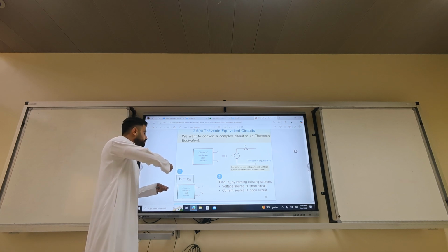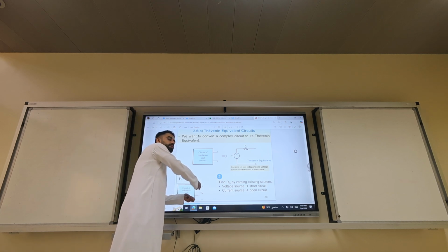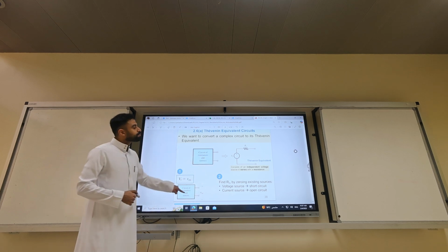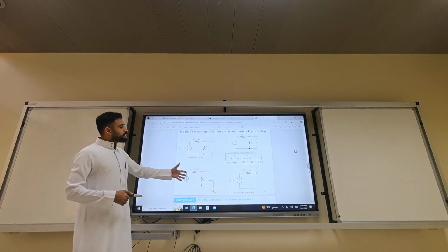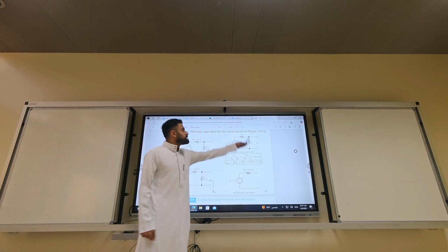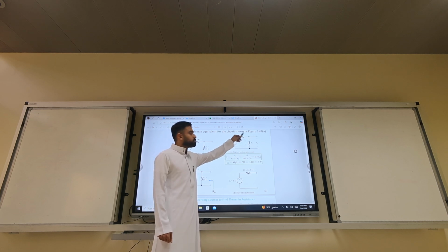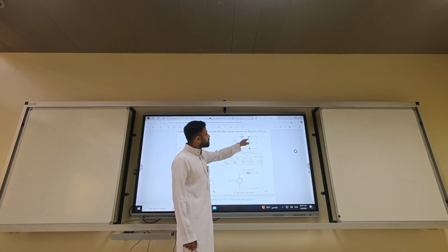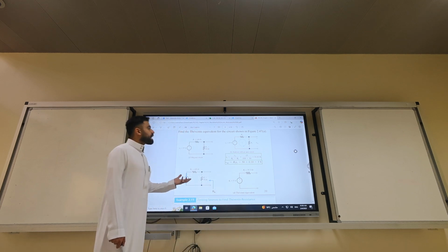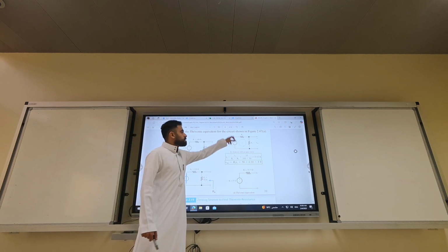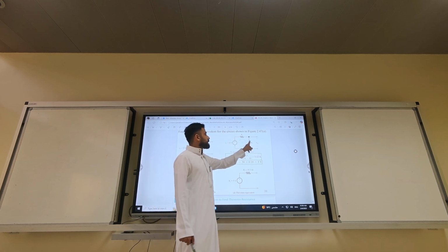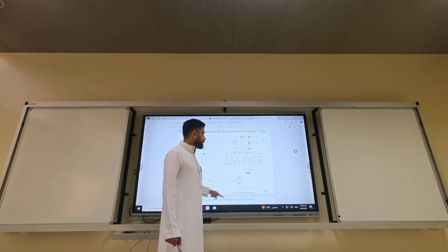We call it open circuit because we're measuring across the open circuit of the spaghetti. Okay? We did some simple example here where the open circuit was nothing but a voltage divider between R2 and R1, because all the current will go through I2. There is no current that will go through these hanging cables. We calculated R Thevenin by shorting the voltage source, replacing it with a line, short circuit, and R Thevenin looking that way, it's R2 parallel with R1.